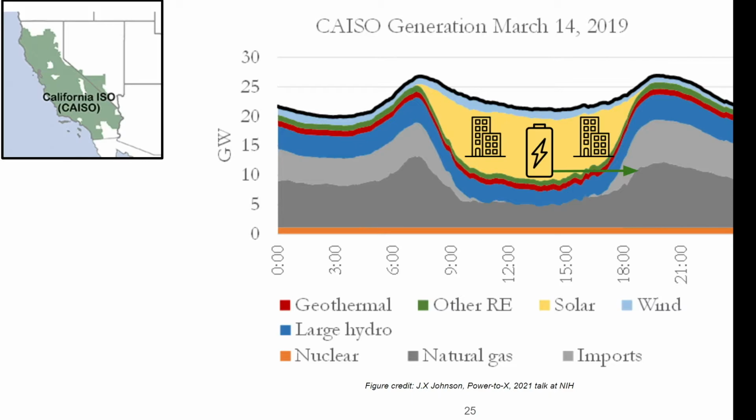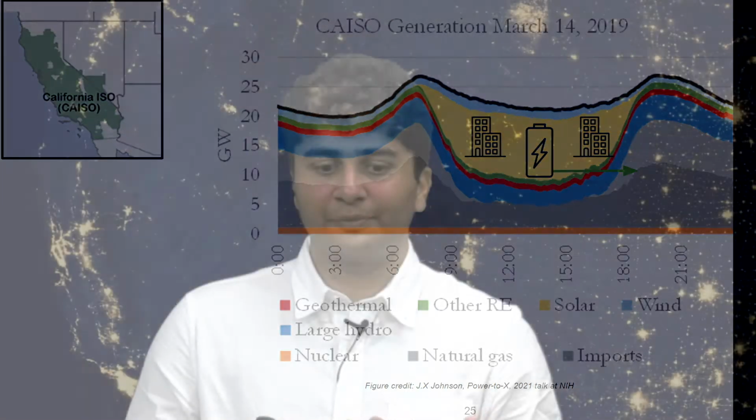If you have buildings in the middle of the day, you could decrease the thermostat so the buildings call for more cooling, such that excess renewable energy is dissipated across buildings. This allows the system operator to integrate more renewables onto the grid. This program is called demand response services, and it's one of the ways on the demand side that can really help us integrate more renewables.